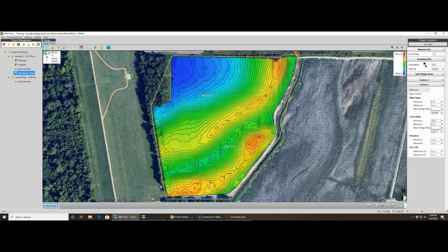Okay, so then we'll go 1 over 300. We can set a minimum and a maximum elevation. I don't use those because generally in this type of scenario we're not importing or exporting dirt. If you have to have a minimum and maximum elevation, you will have to figure import or export. Also the same thing with the cut and fill. So in this video we're just going to do balance just to get a basic overview on how the program works.